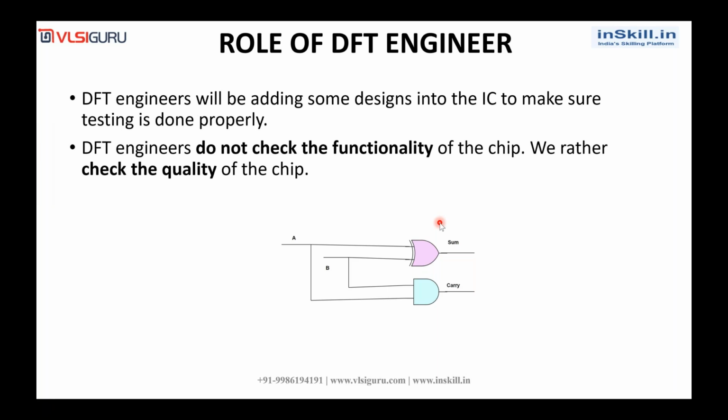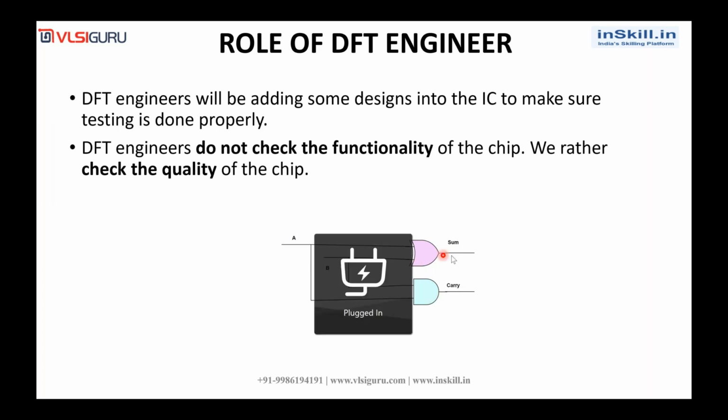DFT engineers do not check the functionality. So what do we do? We check whether each and every net in the design is free of manufacturing defects or not.